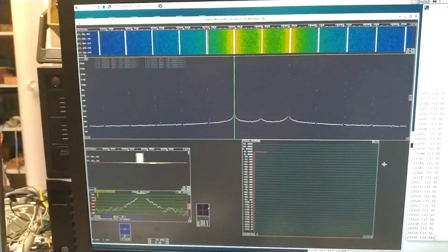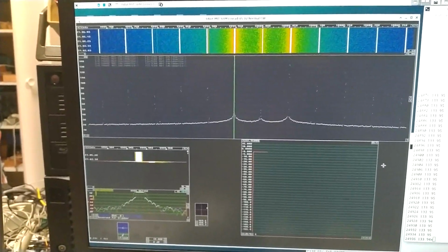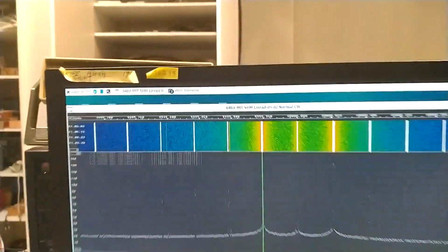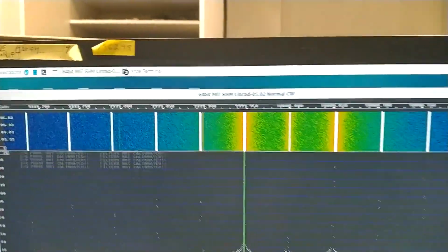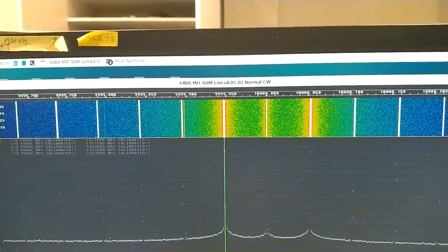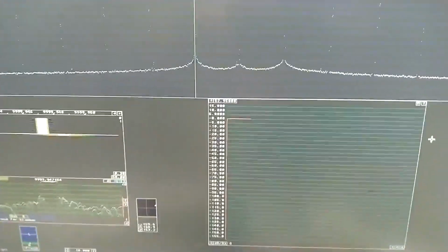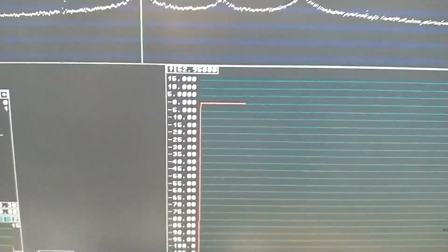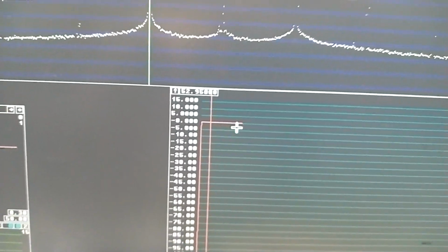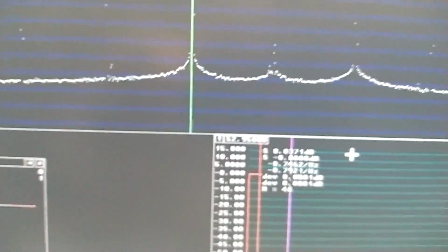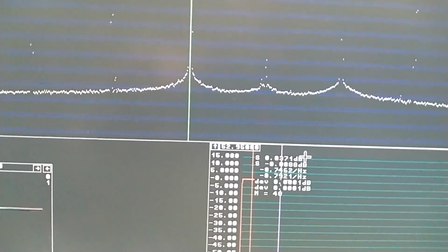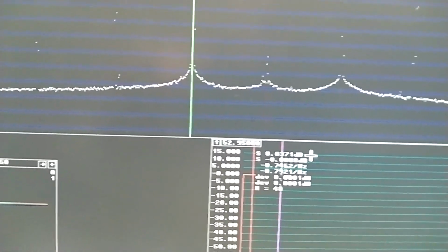I want to look at the wideband noise floor, so I'm running Linrad in normal CW mode. So I have the wide waterfall and then I have the S-meter graph. I have calibrated it, so when I measure the level, I read on the average 0 for the two channels, plus or minus very little.